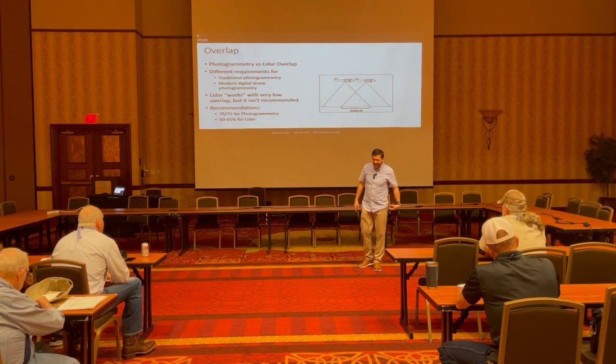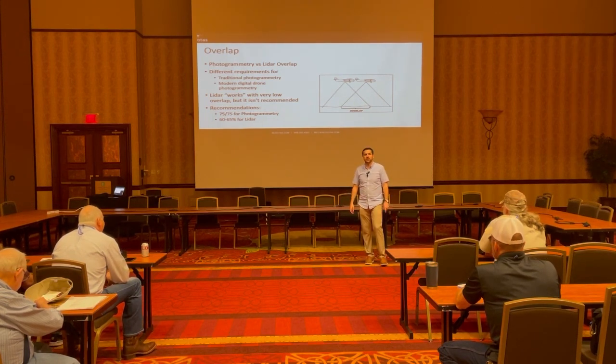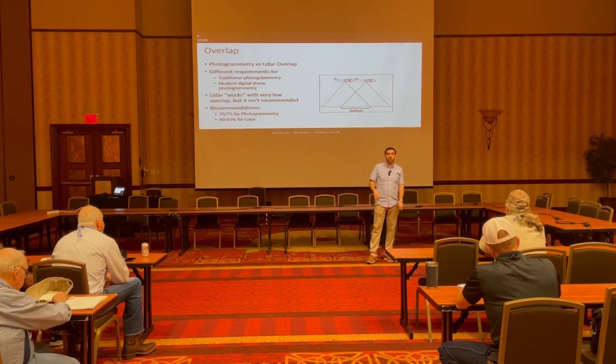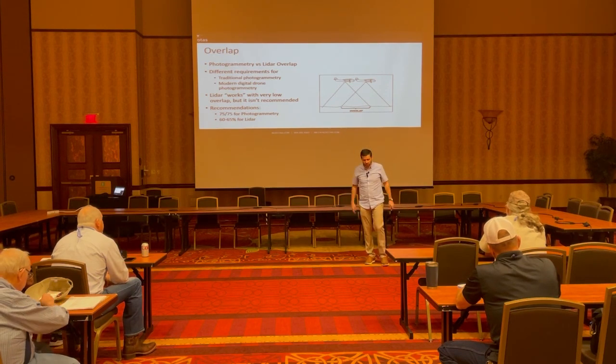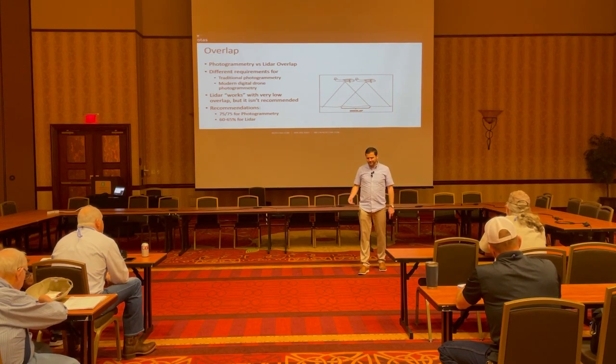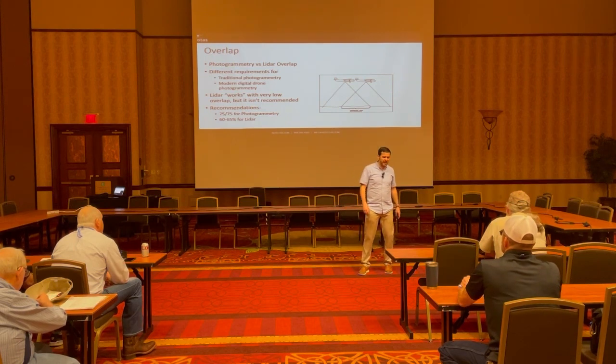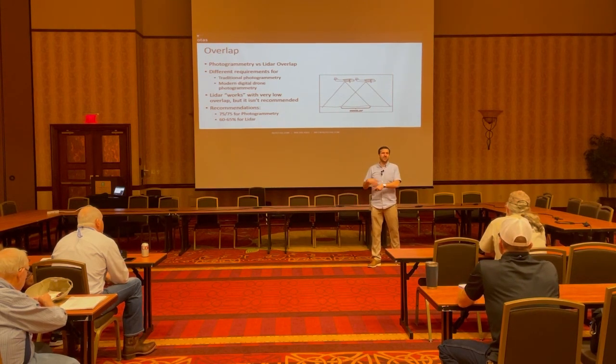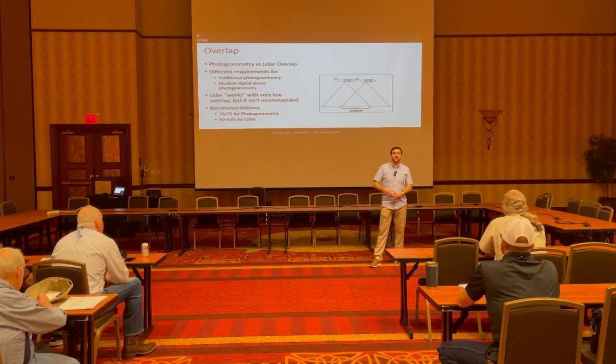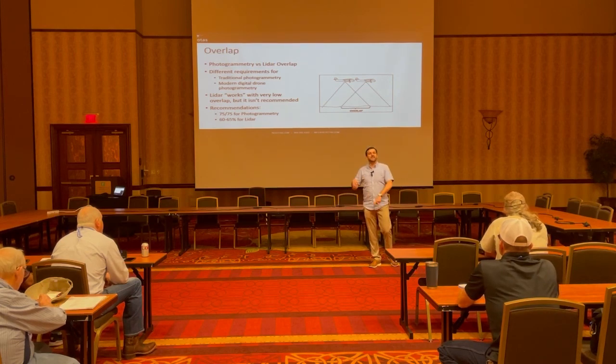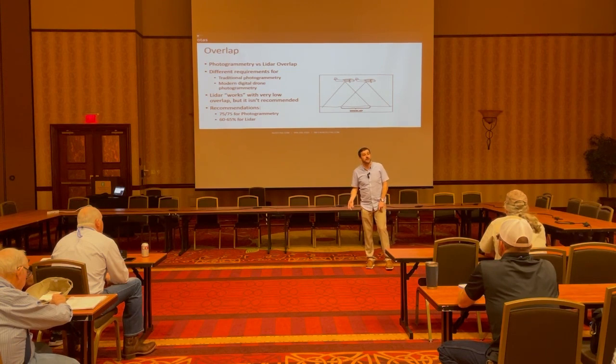While that's technically possible, what I've found is that actually increases the error rate of the overall point cloud, whether the swaths don't agree perfectly, if there's a couple tenths of a foot disagreement there, or if your laser scanner isn't perfectly calibrated or that sort of thing. And also that means your photogrammetry overlap is going to be lower if you're flying it as well. It leads to a lot of requirements to refly the mission if you don't have high enough overlap.